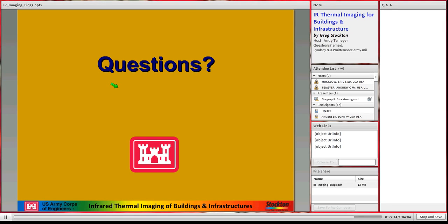I could hear, but the mold question, you cannot find mold with an infrared camera. It does not make an exothermic reaction strong enough for anybody to be able to find it with an infrared camera. As you correctly pointed out, though, where you have moisture is where mold is. So the direct question, it takes a microbiologist to find mold. But you find moisture with the infrared camera, and you'll find mold wherever you find moisture.